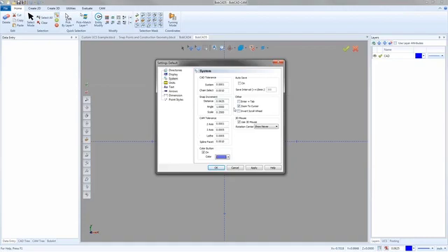Enter equals tab. The way that most Windows systems work is when we hit tab, we go from one box to the next box. So we can see it's just tabbing through there. Again, shift tab goes back up in case you wanted to know. Enter in BobCAD does not move from one box to the next. Enter creates geometry. So if you're in the middle of creating a piece of geometry, like a rectangle or an arc or what have you, and you designate how big it's going to be, and then you hit enter, it's going to create it. It's not going to update the preview. It's going to create whatever it is that you're currently on.